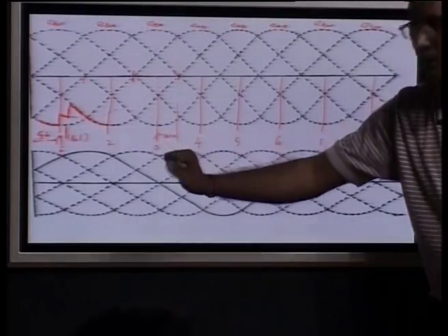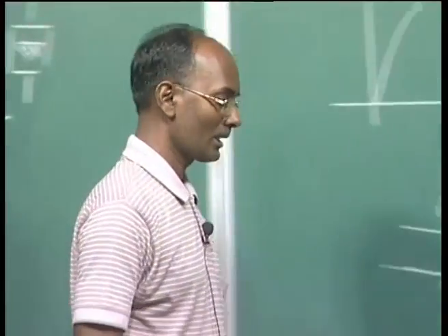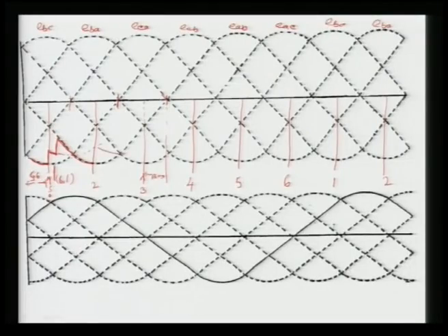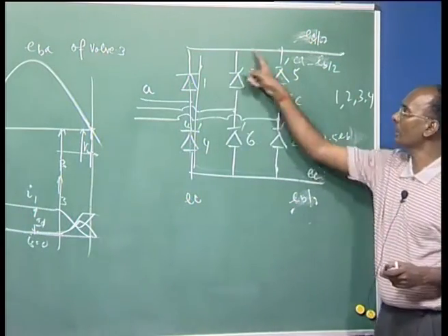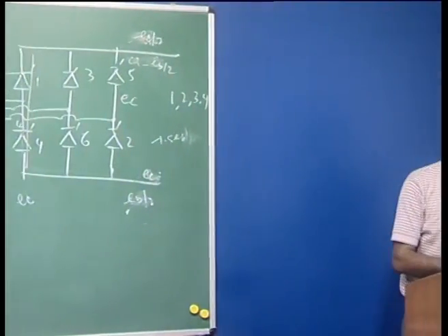and now there will be commutation between 6 and 2, and we will find the sequence. Now you can see from here the voltage will be again like this, it is going something here, and then again the voltage will be like this. Means during this your 1 and 2 are conducting, you can see 1 is your EA, here EC, AC, A minus C, so EAC will be the voltage here.